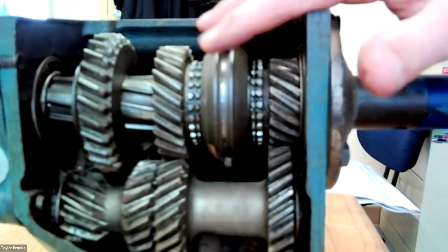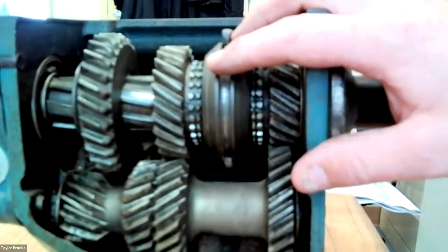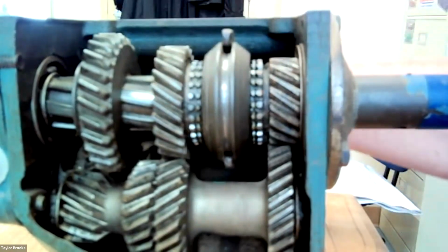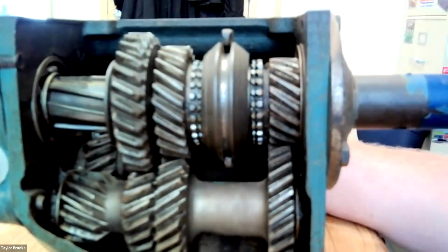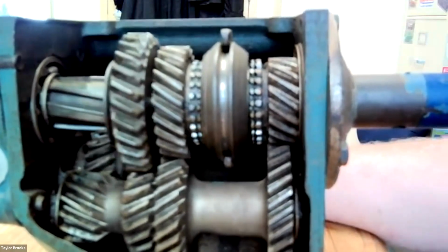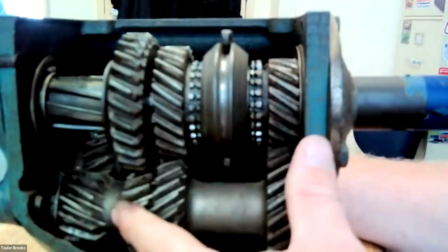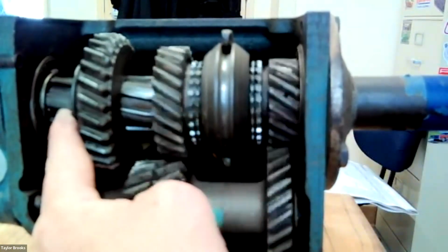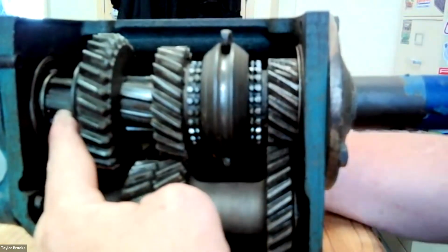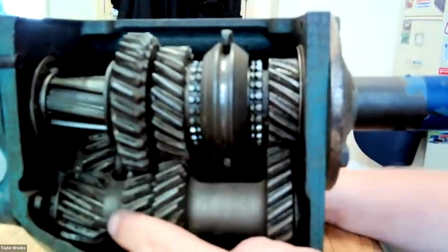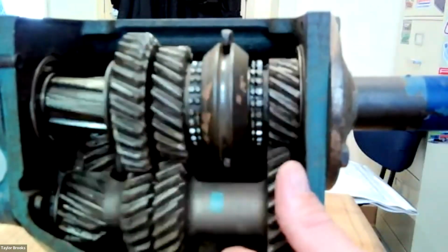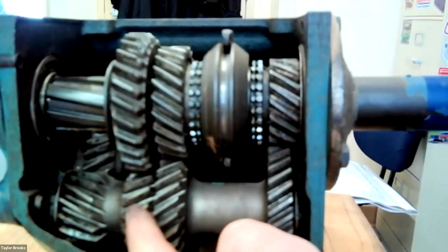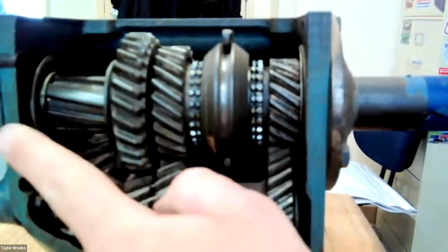Now, I did bring up that the synchronizer is the more modern method, and this transmission has a mix of both. Our first gear is up here, and when I'm shifting it into first gear, I'm actually physically moving the gear in place. This is how transmissions shifted before synchronizers. So with it in neutral, the output shaft isn't turning. When I shift it into first gear, I'm physically moving this gear into place, and now my output is allowed to turn. I'm going down through the counter shaft through my smallest gear that's cast on here, and then up to the output.